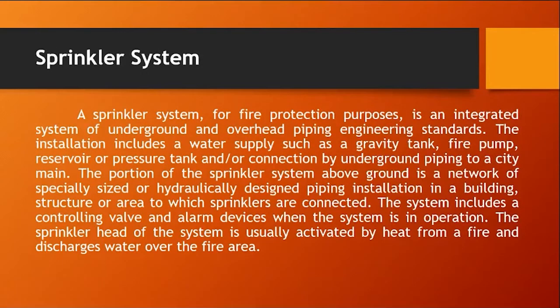So, sprinkler system. Ayan, sprinkler. A sprinkler system for fire protection purposes is an integrated system of underground and overhead piping engineering standards. The installation includes a water supply such as gravity tank, fire pump, reservoir pressure tank, and or connection by underground piping to a city main.